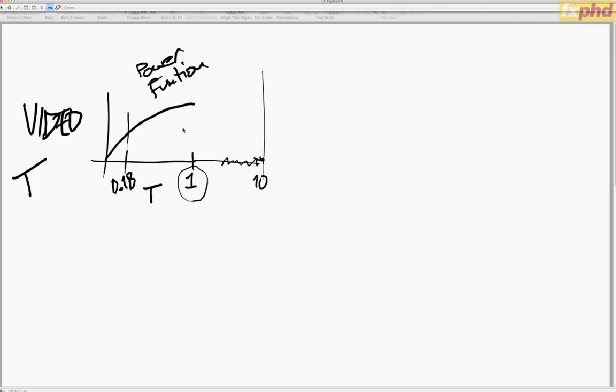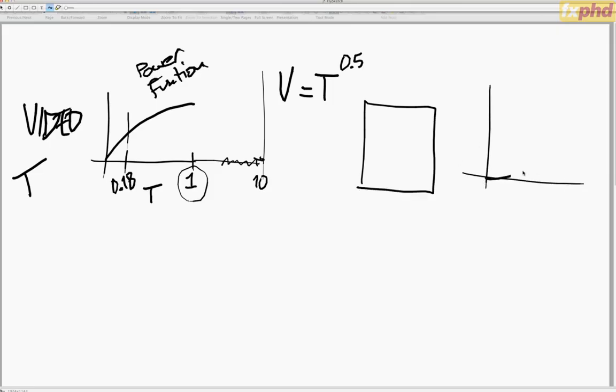So we take a power function, we form video as something like tristimulus to the 0.5. Then we work in the video domain, and then at the end of the process, we go out, video raised to the 2.2, or maybe it's a 2.4, maybe it's a 2.6, into linear light that we present to the viewer. So this whole video thing, it's all about power functions.